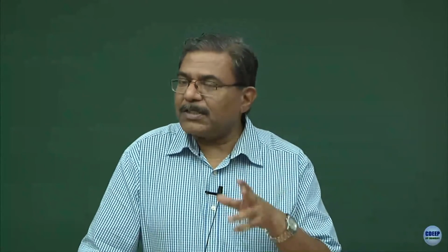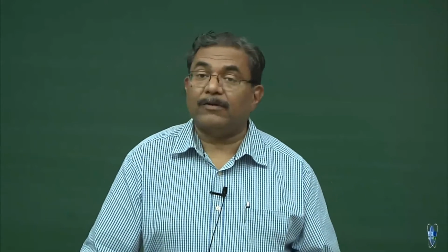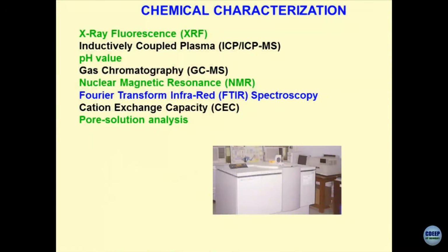So, when this type of questions come in mind, that suppose if I have to evaluate 2-3 materials and if I have to chalk out a strategy that where what type of material should be utilized, and this is where we talk about the chemical characterization of geomaterials. This is an intricate subject. So, earlier we talked about XRD, if you remember, X-ray diffraction. Now, I am talking about X-ray fluorescence, XRF. So, XRF technique gives you the chemical composition of the material. It could be elemental analysis and the percentage oxides which are present in the material, XRF we call it.